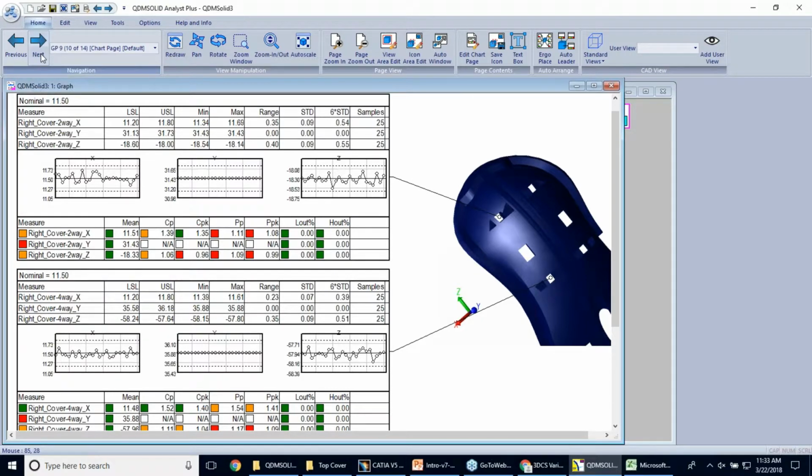So say in 3DCS you measured a point that was 1 millimeter from a corner, and the CMM guy measured a point that was 4 millimeters from the corner. If you want to assume that the variation is going to be the same right there, you can link those 2 points, and then you don't have to mess with the uncoordinated points.